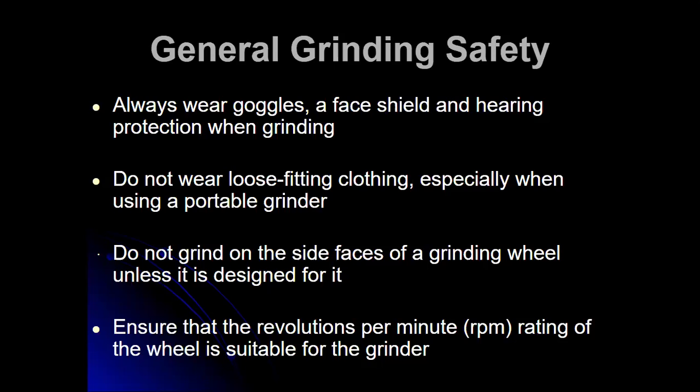I could apply the same to ladies with long hair, gentlemen with long hair. But what we mainly deal with in here are hoodies, hoodie strings, earbuds, things like that. We do not want those near any high-speed rotating equipment. It's going to grab that and start to wind up that hoodie string. And we all know those hoodie strings sit just below our chin. So that grinder is going to come flying towards our face, and hopefully you are strong enough to stop it. Things could end up real bad, and I don't ever want to see that in my shop.